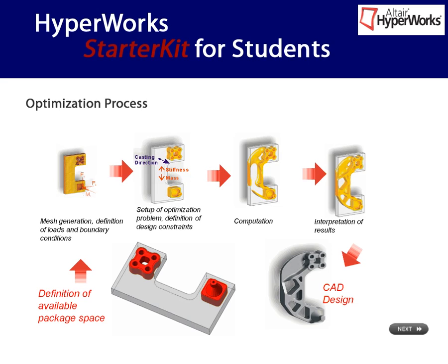After the optimization setup is complete, the iterative run is started. The optimized design resulting from the topology optimization is a conceptual result, which needs interpretation, followed by redesign in the CAD system and a reanalysis to validate the optimized design. I am sure you will be thrilled by the process and its results.